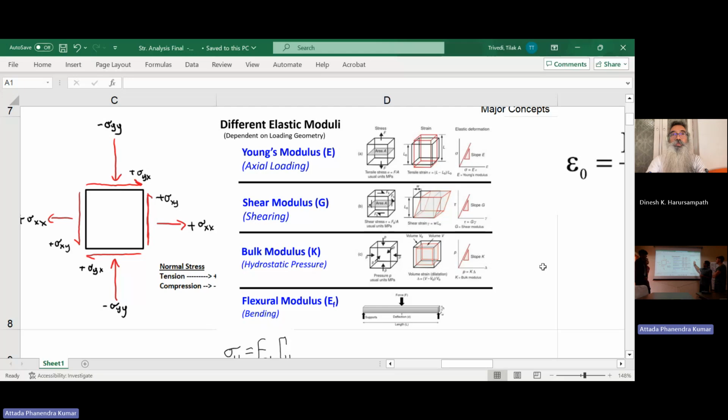And in this case, you can see that it assumes much of the assumptions that we made in class, where it's elastic, the relationship is linear, and that's how we would get the slope, which is how you get the Young's modulus. But we'll see later on that that's not necessarily the case. There's a less assumption-heavy and more precise version that we can use.